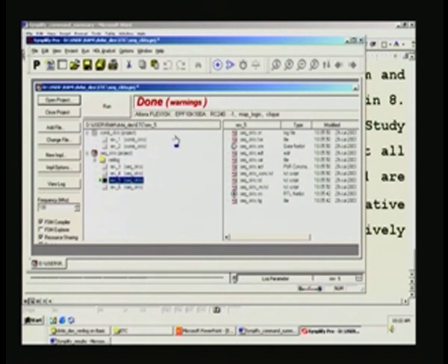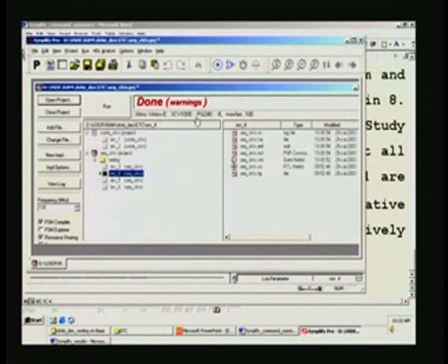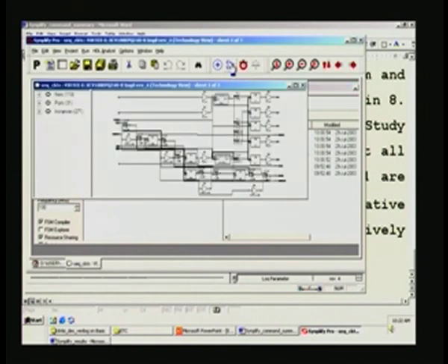And first we will have a look at the technology view before we proceed. Let us see, we will go for this XCV100E PQ240-8. This is the highest speed available in 100,000 gates capacity. It can accommodate approximately 100,000 gates plus RAM as well, and it is a 240 pin package, and this is the highest speed. And let us view the technology view.